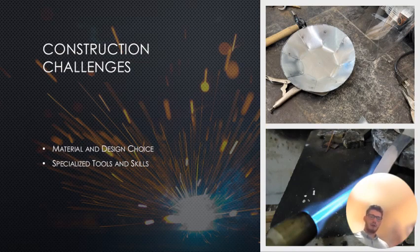Also, because of the material, I needed to use a relatively thin gauge or thickness of sheet steel, and this caused problems with the fastening method. For any of you that have welded, welding sheet metal is difficult, or at least it is for me because I don't have a ton of experience. Working with such thin material, it's easy to burn through, and it's important to practice and adjust the welder accordingly.